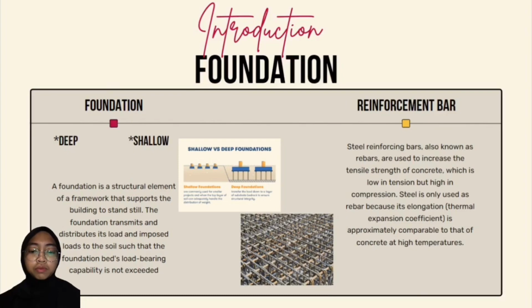Even though the material has appropriate qualities that make it able to provide suitable application for foundations, subgrade walls and footings, it is, however, weak in tension and susceptible to break as a result of shrinking or creeping under sustained load. Rebar's prime objective is to carry the structural and external loads exerted on a structure to maintain it from